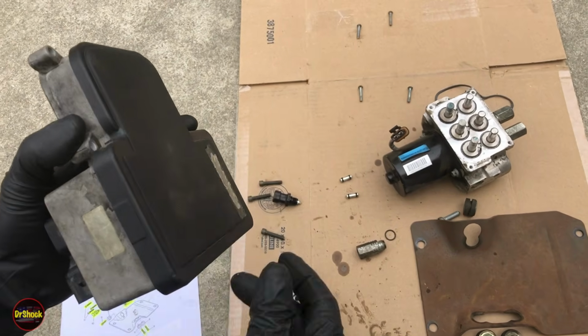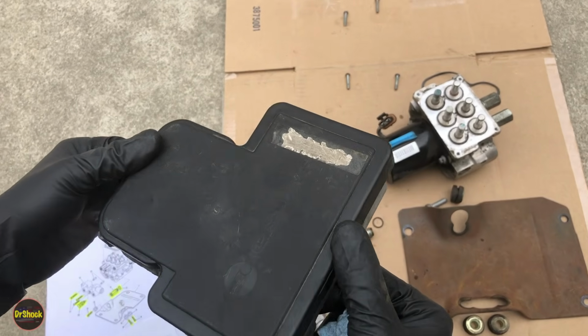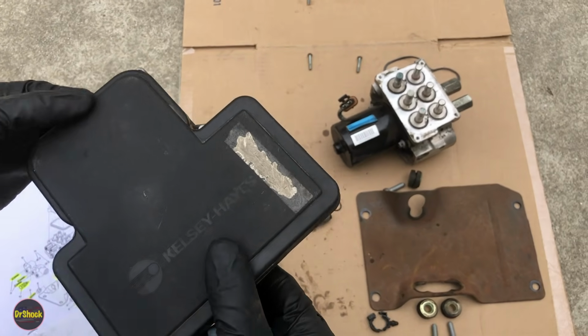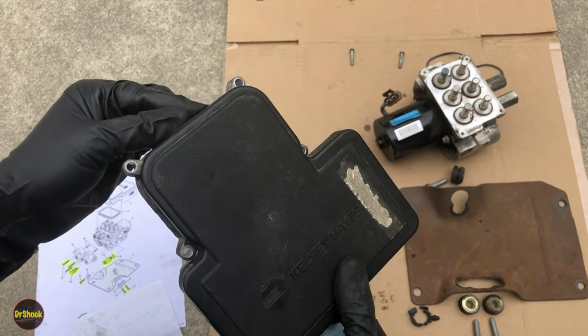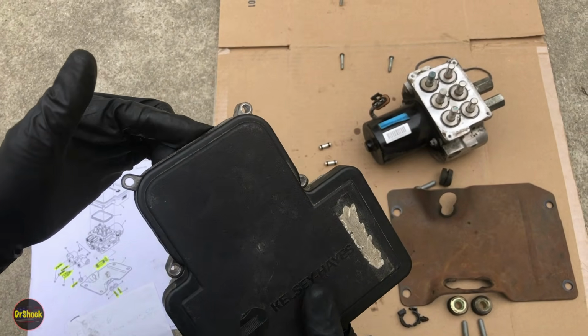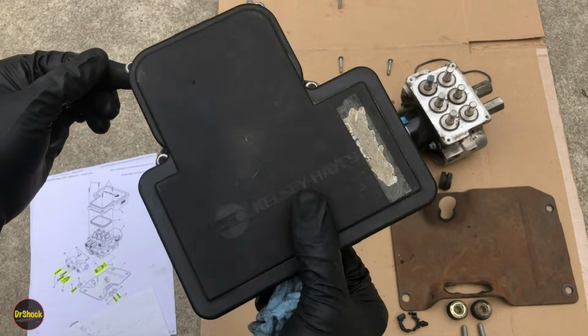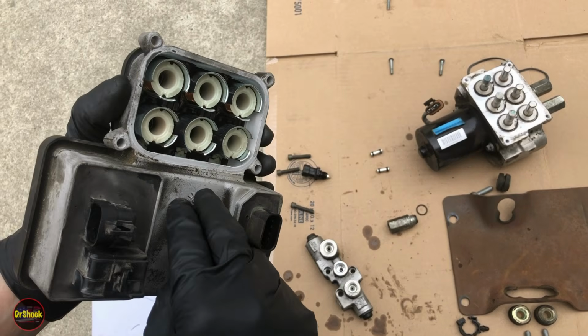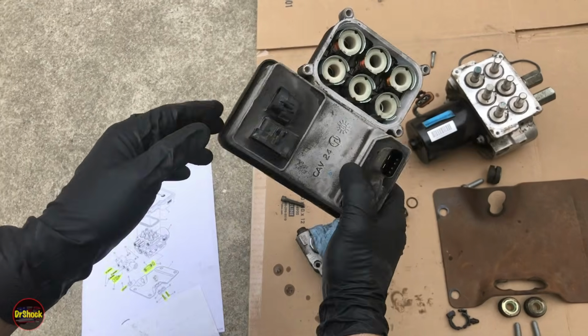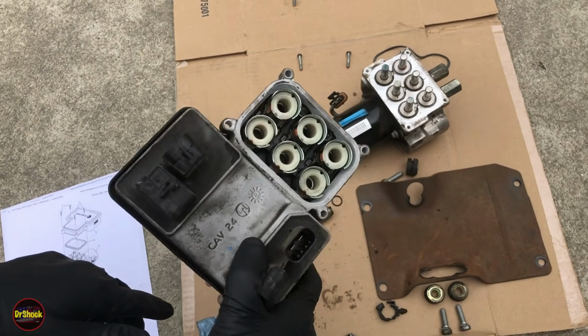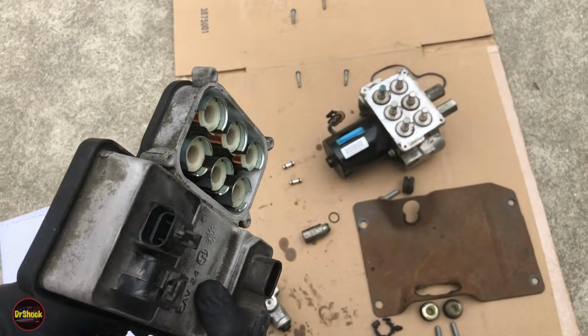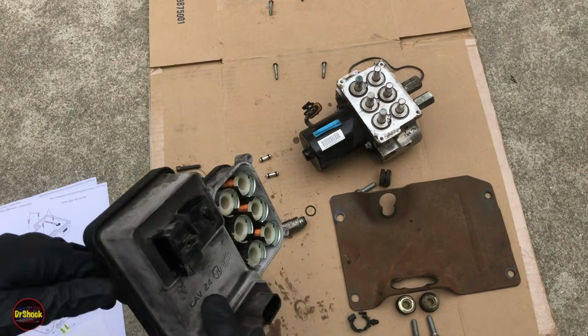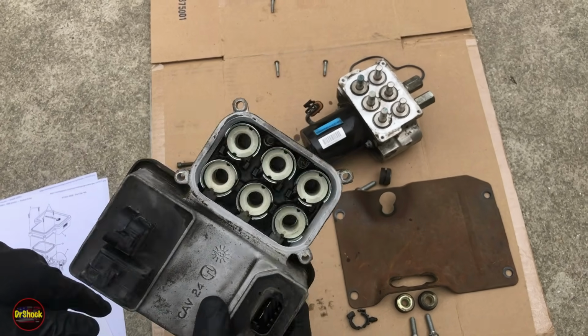For example, the one we needed in this truck, we needed an EBCM that was compatible with either JB7 or JD7 brakes. That is not the same as the EBCM for JD6 or JB6 brakes. So all of these computer electronics are geared to operate these valves differently depending on the axle of the truck, the engine on the truck, the transmission on the truck, the weight of the truck. So all very important considerations.